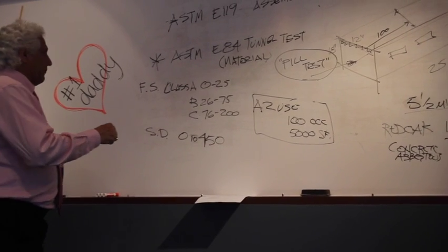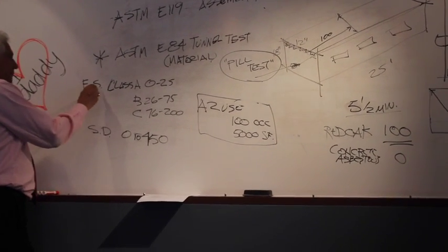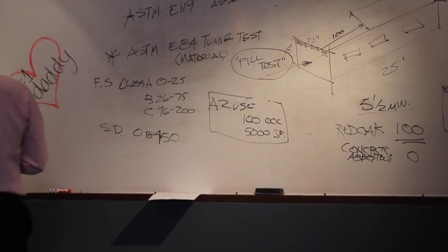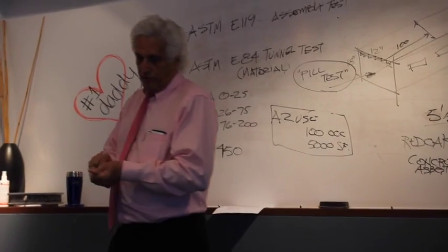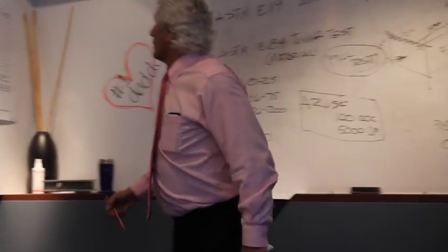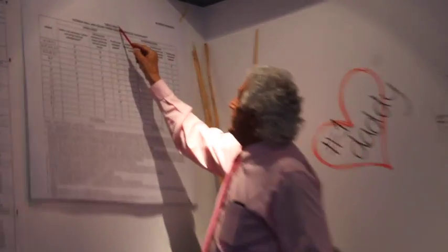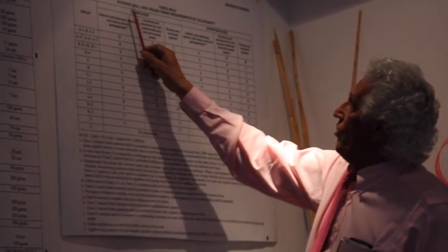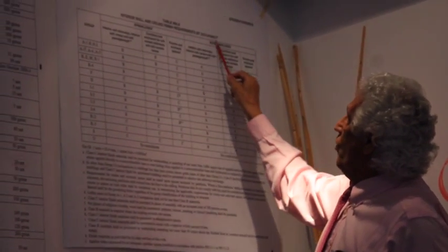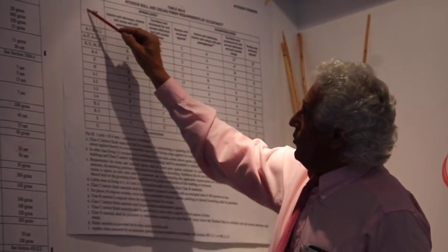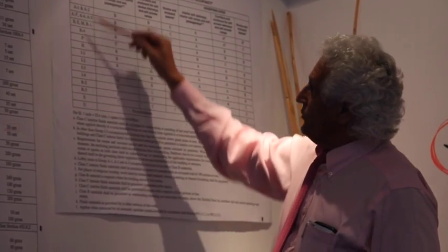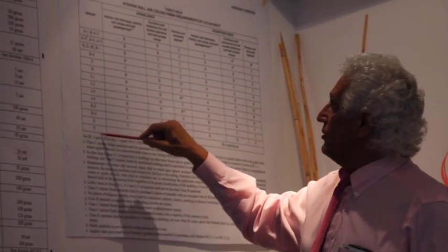I did want to back up for a minute and talk about this flame spread rating, because one of the charts that's in the code is related to that. Table 803.9, what this talks about is the wall and ceiling finishes in occupancies in different components of buildings. So again, we go back to our 10 groups here that are listed.